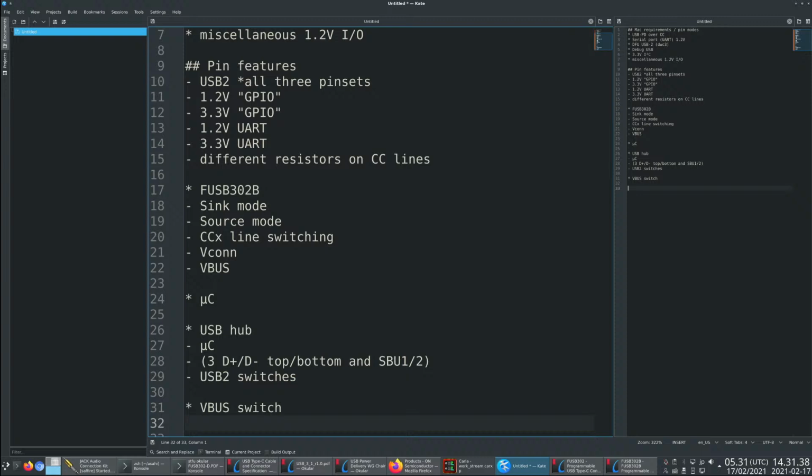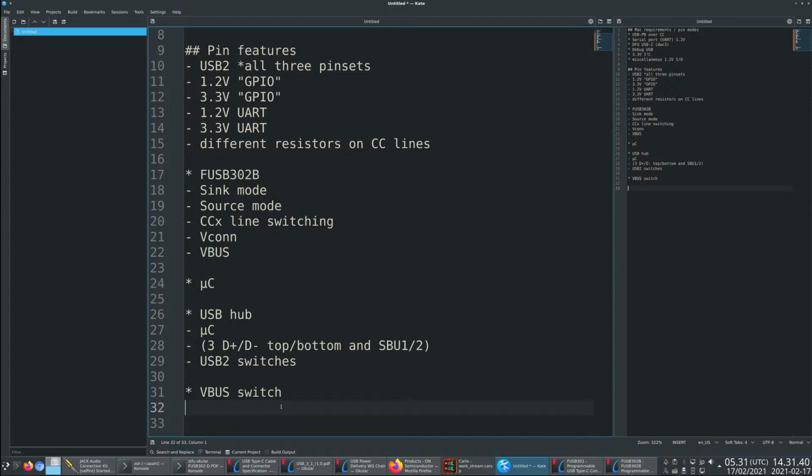But either way, we need to support the use case where we want to provide VBus power. And so there needs to be an external VBus in connector where you could plug in 5 volts at least if you want to just do a standard power supply, or if you want to extend this into a test platform for USB PD configurable power supplies.